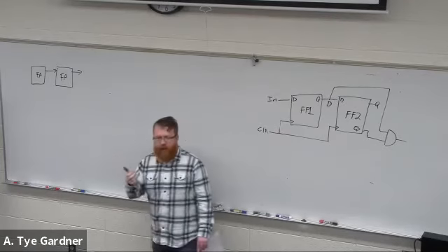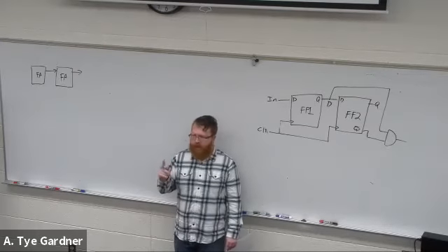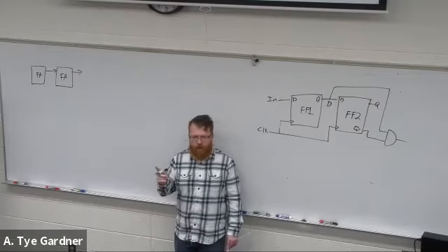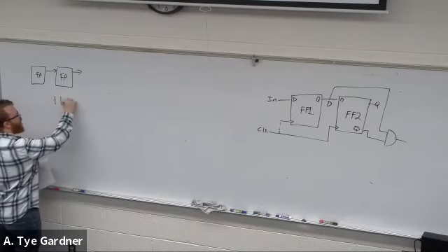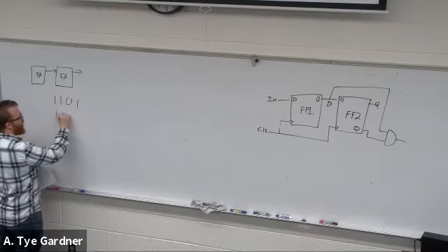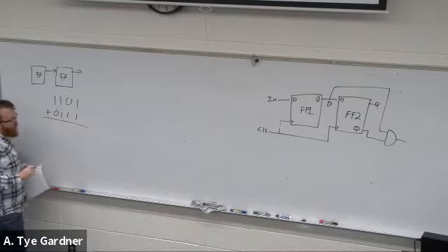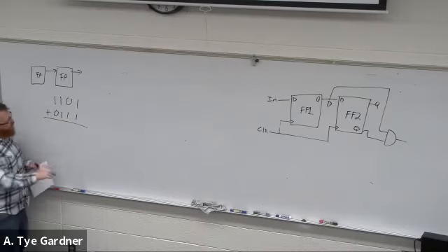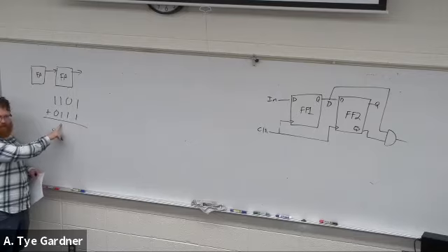So what the carry look ahead adder does is it realizes the assumption that we know, given 2 numbers, that if I'm adding these 2 together, I can already tell that this column is going to have a carry out.